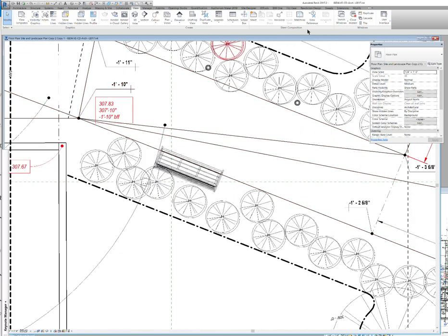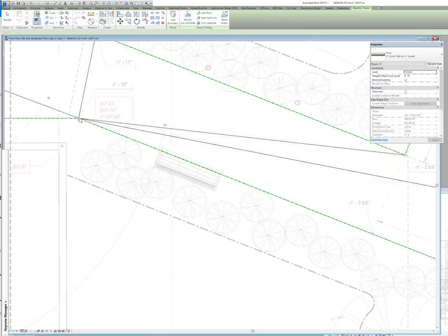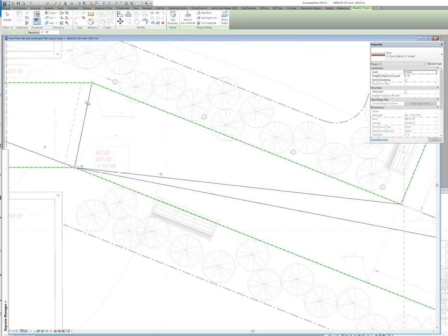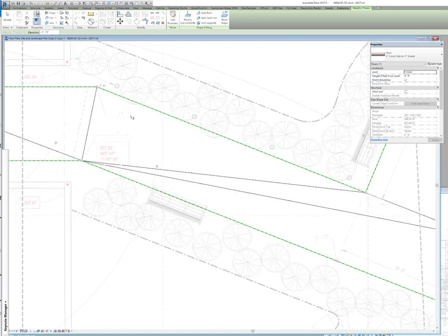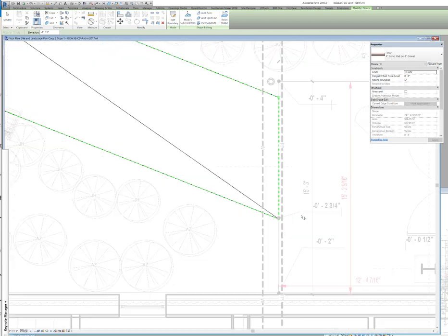So the first point I'm going to set in using that modify sub-elements, so I go into this, so I want to set this at negative 1 foot 10. I want this to be an inch below that, because remember, 8 feet, that's another inch down. I want this to be at negative 1 foot 11, all good. And I want this to be equal to the negative 2 3/4 inches that I picked up over here. So click, I set that to negative 2 3/4.